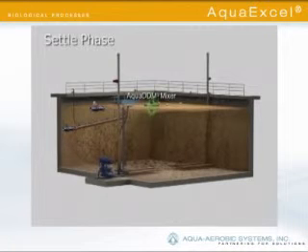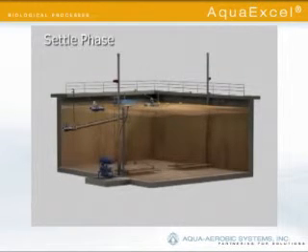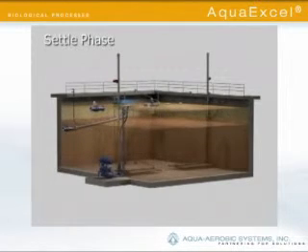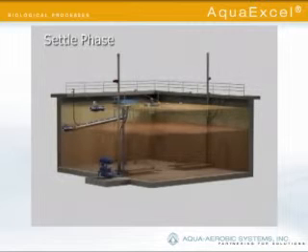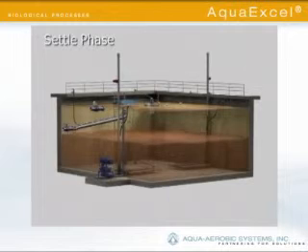In the settle phase, influent flow is terminated while mixing and aeration remain off. Ideal solids-liquid separation is achieved due to the quiescent environment, allowing the reactor to function as a perfect clarifier. As with all of the treatment phases, operational flexibility allows the user to adjust the settling time to match the prevailing needs of the plant. Due to the batch feature of this process, the settle phase is unaffected by variations in flows that cause disruption to settling in conventional flow-through secondary clarifiers.